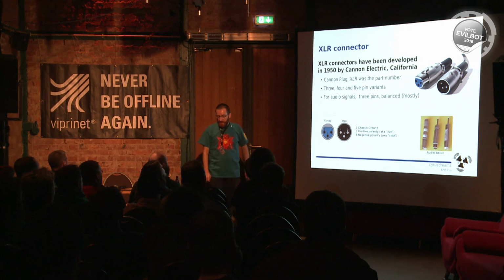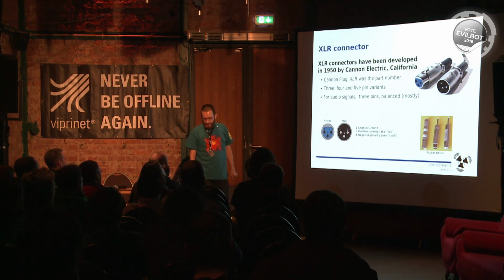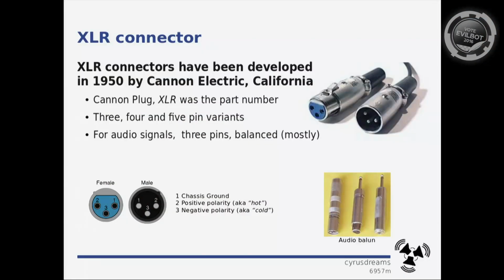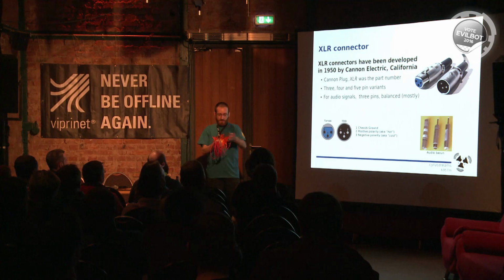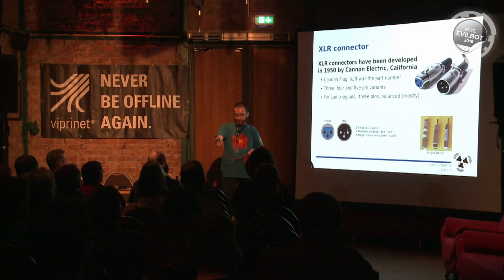And the phone plugs, well, they unplug quite easily if you pull on them, and then there's this confusion with balanced and unbalanced and stereo. So what is most of the time used for audio connections from one point to another is XLR connectors. XLR is what I have here. You have the size, you can see it. That's an XLR connector, male, female.